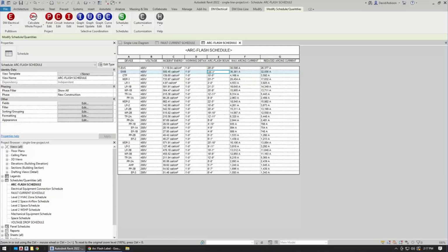When you're trying to match your breakers, if it's an existing situation, pictures of the breaker are always really helpful because you never know which settings on the breaker are going to have an influence on the curve. Because the manufacturers will have one curve that'll cover like 10 different breakers, but there's one setting that matters. So if you're doing field work, do your best to get as many pictures of those breakers as you can, so that when you're trying to look them up, you have the information available.